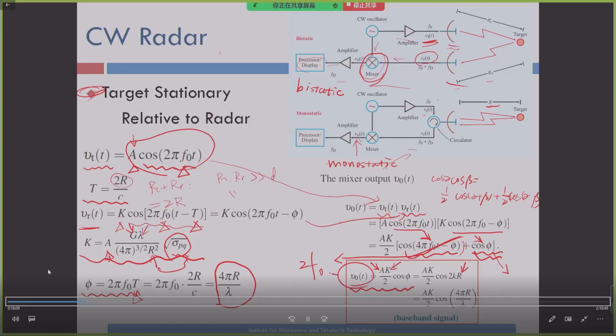So then we obtain the cross-section here, and as we introduced, if we know the cross-section, we can get some information about the object, such as its dielectric constant, alright? And also sometimes we get the size or its shape or its surface properties, such as its roughness, and many parameters that we can obtain by the backscatter cross-section from the radar system. So, when we come back here, now we can obtain our received signal by this one. So, based on this one, we have the simplest model to express how the radar signal propagates in free space due to reflection by an object.